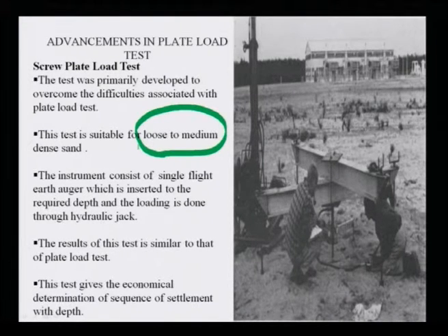The instrument consists of a single flight earth auger which is inserted to the requisite depth, and the loading is done through a hydraulic jack, you can see it here. The results of this test are similar to those of the plate load test. The test gives an economical determination of settlement with depth.